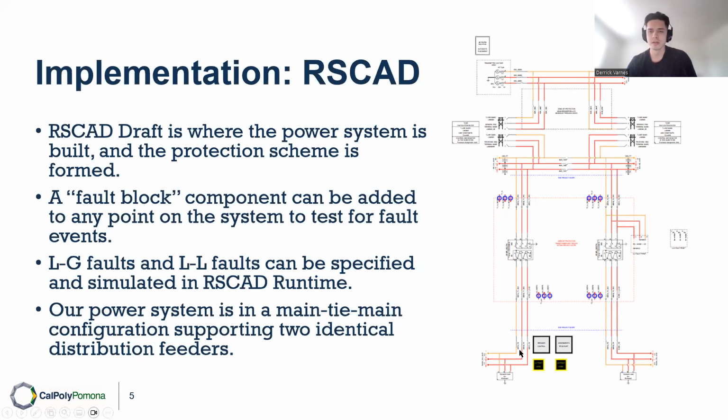And then at the bottom here, on the load side, we have dynamic load blocks with predefined load values that give us some very workable currents to make setting calculations a little bit more simple in the 387A relays.